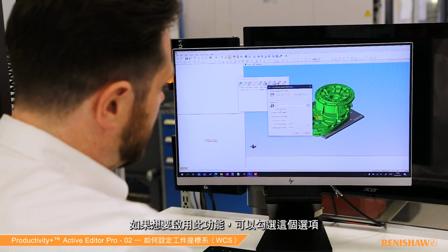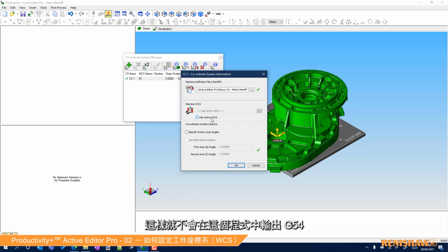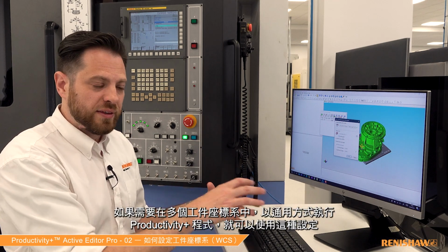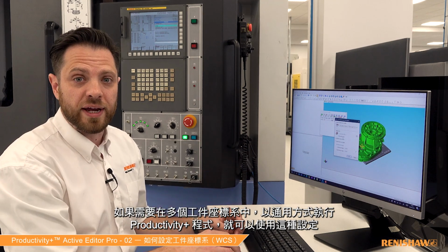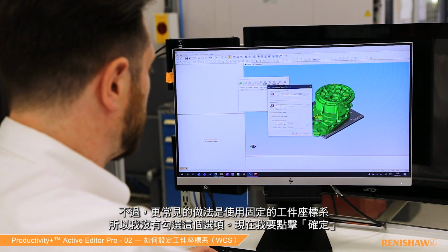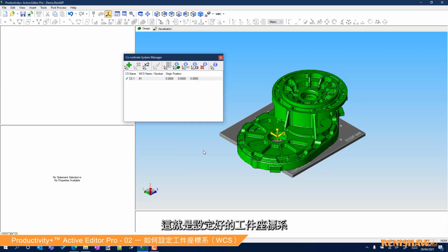If you want to do that, you can flick this switch here that says Use Active Work Coordinate System. That means we will not output the G54 in this program. We will not output any work coordinate system in the program. We'll allow a main program to determine that. That's how we can get around that situation where you want to use the Productivity Plus program in a generic way across multiple work offsets. More commonly though, we are going to be working in a fixed work offset, so we can leave it as that, and I'm going to hit OK.